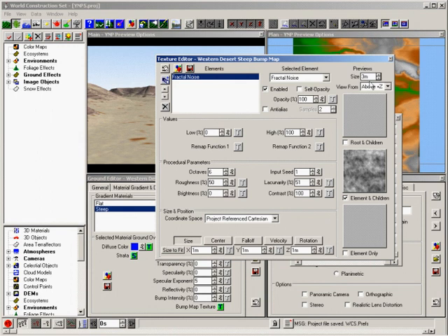The thumbnail shows a 3-meter wide sample of the fractal noise. Increase the preview to 10 meters and view from to cube. Change the element to multifractal, the X and Y size to 5,000 meters, and the Z to 50 meters.